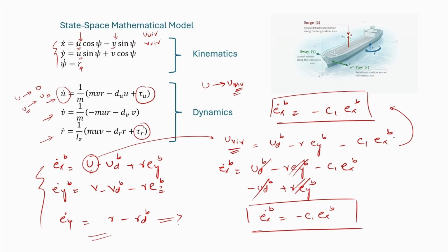Okay. Now we will follow this same process for the sway angle. But the problem is that it does not have any control input. So what we are going to do is use this yaw error for that case. So how are we going to design this R virtual? Same process, because our aim is to achieve this asymptotic stability.